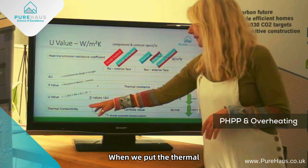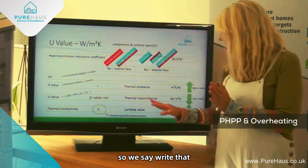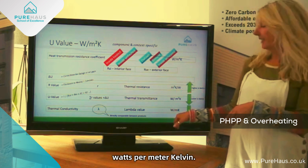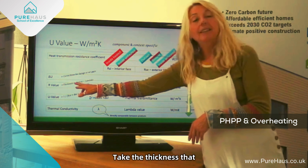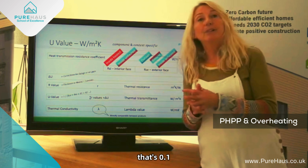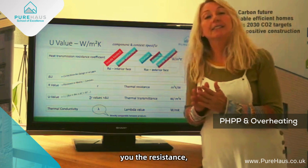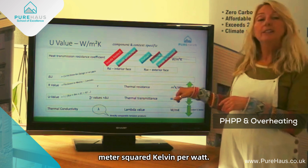When we put that into a building, we say, right, that insulation has a lambda of, let's say, 0.03 watts per meter Kelvin. Take the thickness that you want to use, for example 100 millimeters, that's 0.1 of a meter. Divide it by the lambda, and that gives you the thermal resistance, in meter squared Kelvin per watt.